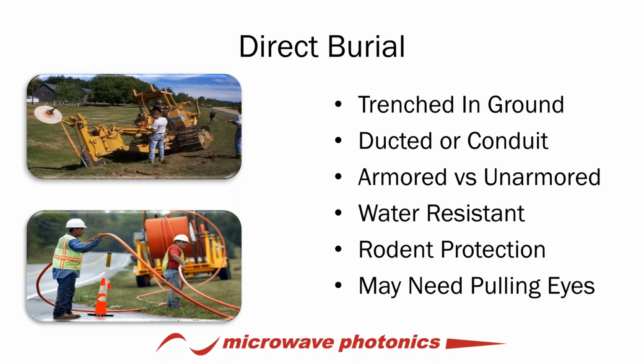And then there's a whole different set of considerations for that cable. Is it water resistant? Do you need pulling eyes? Is it going to be trenched? Or are you going to pull it through a duct or a conduit? How do you maintain bend radiuses? These are all very important considerations.